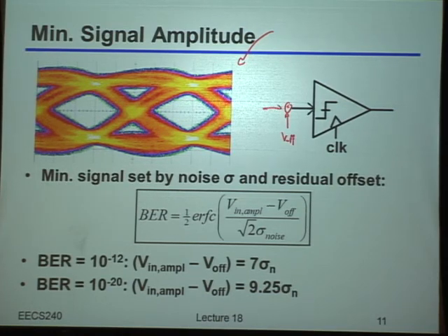Okay, so the question was about this offset voltage that I mentioned last time, which is I said that any comparator you build always has some offset in it. And so the question was, well, isn't that thing sort of deterministic? So the short answer is yes and no. Depending on how you've built that circuit, there could indeed be some truly deterministic offset. By deterministic, I mean that you could have predicted from the get-go that that offset was going to be there.